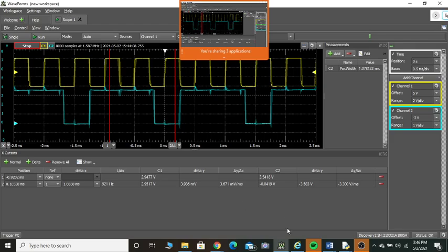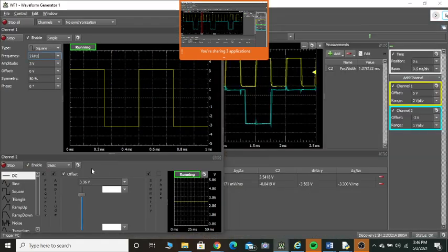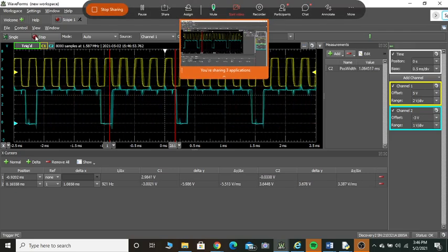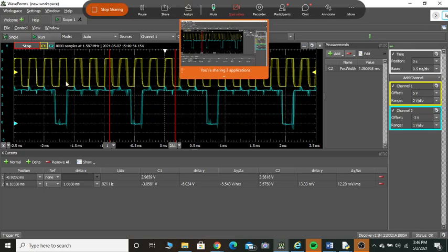Suppose I increase the frequency of this to maybe around 4 kilohertz, you can see how it happens. I will run this. Can you see I'm giving repeated signals? See here, this is valid, invalid, invalid, invalid, invalid. These many are invalid. Why are these trigger signals invalid? Because the output is still in quasi-stable state, these will not be considered as valid.